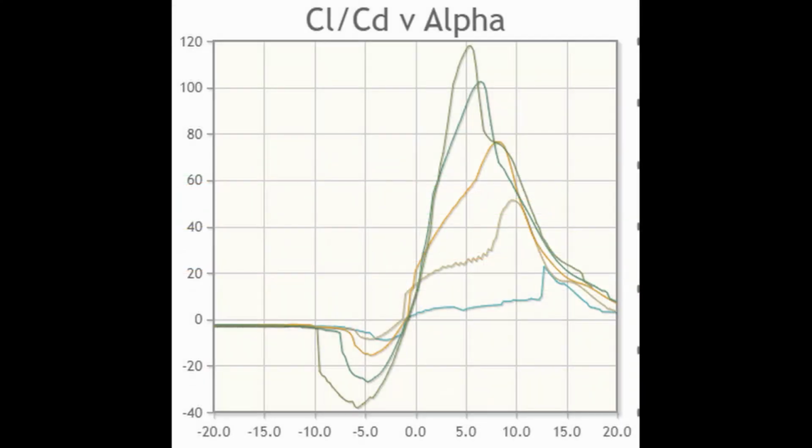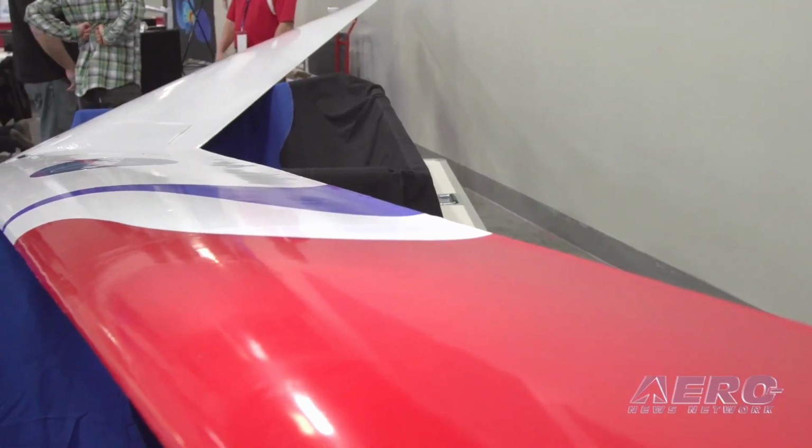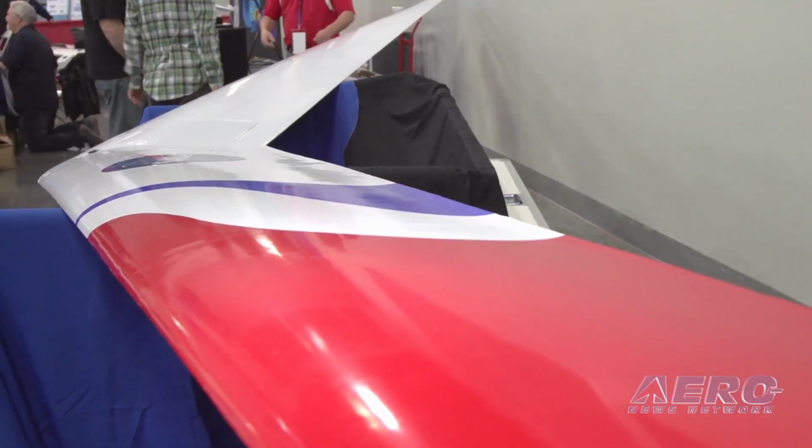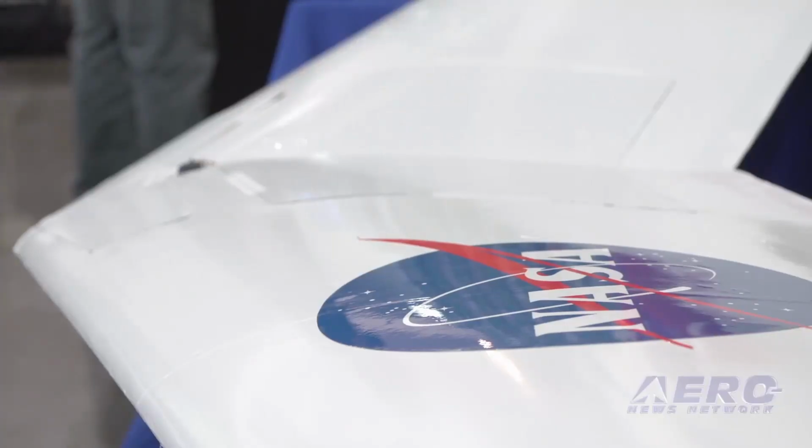For the Reynolds number of cruising conditions, approximately 2 million, it has a maximum lift-to-drag ratio of approximately 75, at an angle of attack of about 5 degrees. The next step in the project consisted of determining other important factors of our wing design, such as the angle of attack, chord, and wingspan of the airfoils.